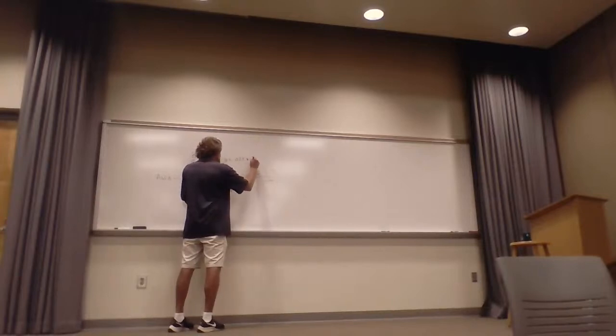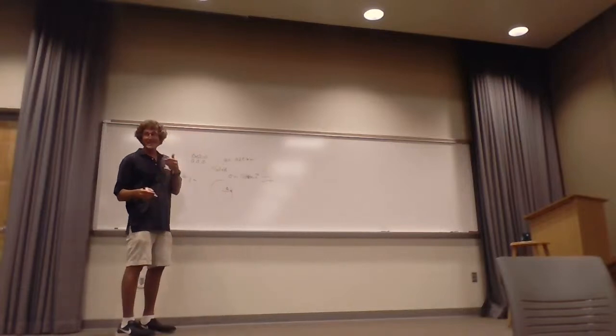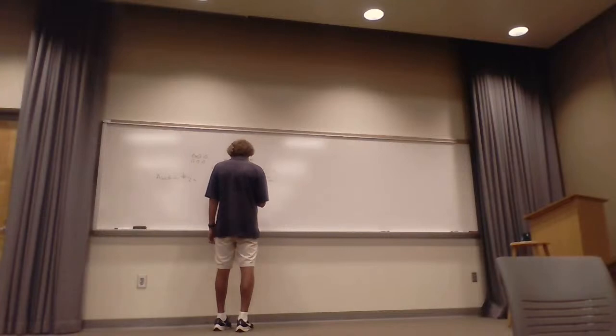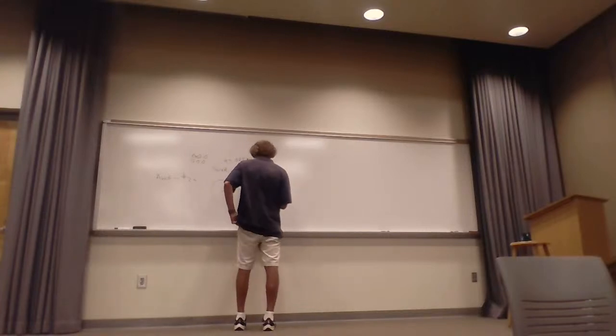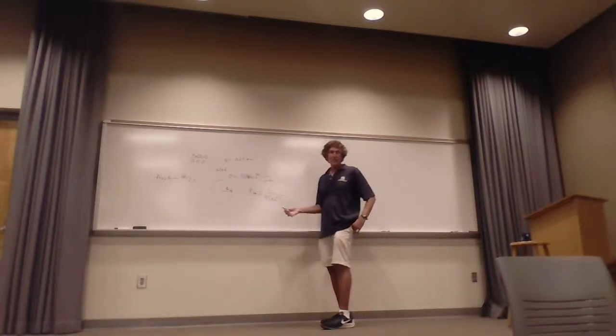0.25 millimeters. Okay, so with that in mind, if we want the per unit length DC resistance, it's pretty straightforward. Our DC resistance per unit length would be equal to 1 over sigma times the cross-sectional area, which would just be pi a squared, right? There's your sigma. You gave me A. Can you give me this, guys? You have your calculators and computers, right?